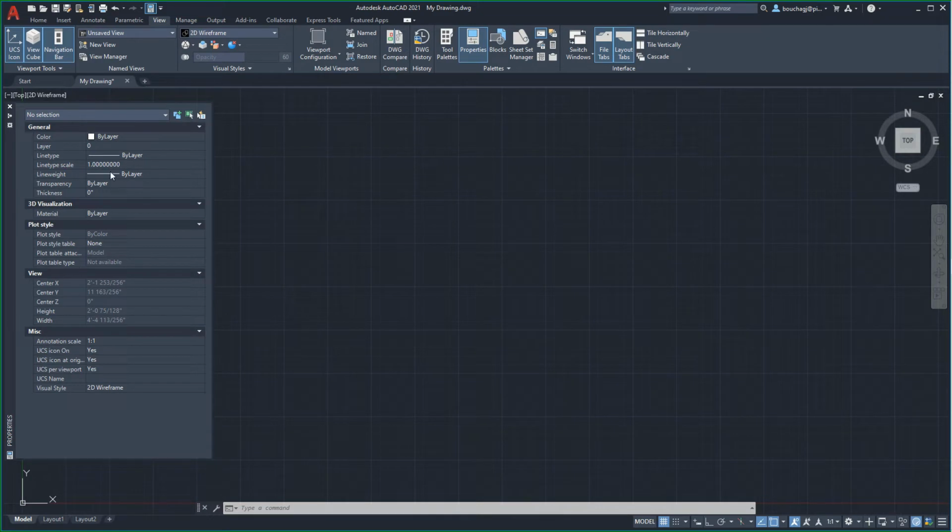The text bar at the top of the Properties palette displays the type of object that is selected, and as appropriate, the total number of objects selected. When more than one type of object is selected, for example, one line segment and one circle, this text bar will display the word All, followed by a numerical value in parentheses, indicating that multiple unlike objects are selected.